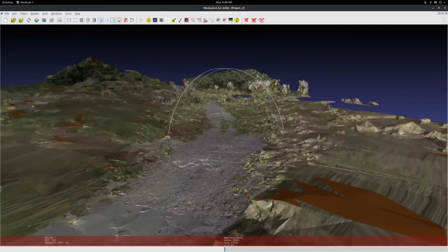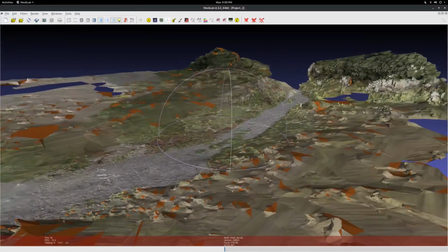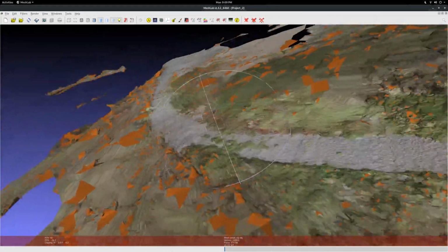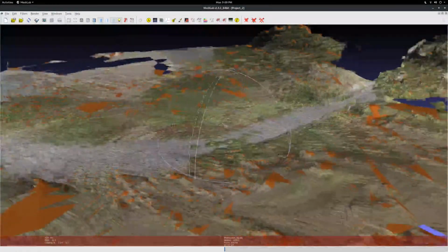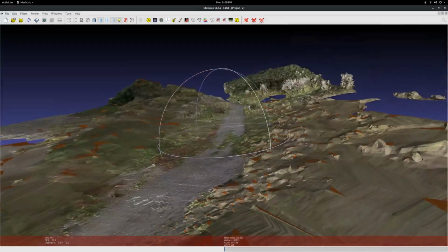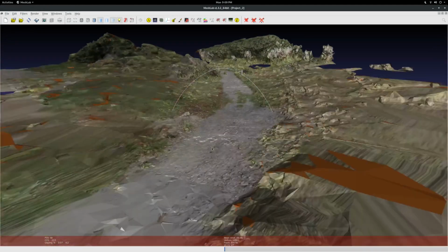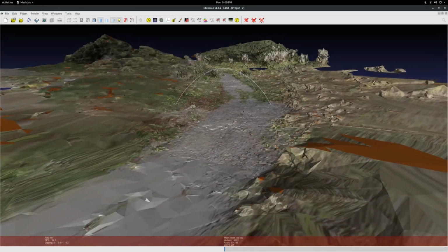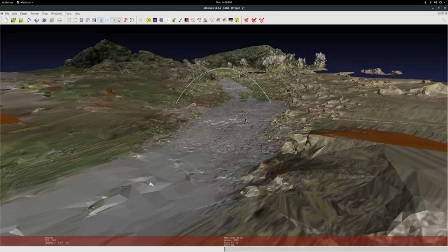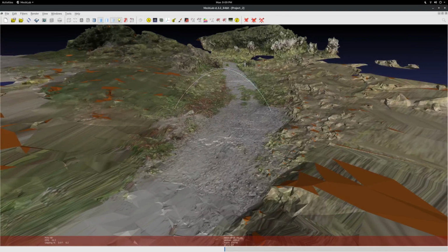If you take a look at this, this is a 3D capture of a trail. You see, unfortunately, a gap in this capture right now. But I generated this by taking video with my cell phone, and then using a process called photogrammetry, I was able to convert the video. I took 3 frames per second out of the video, took a folder of images, and set up a Google Cloud Compute instance with some software called OpenSFM, which stands for Open Structure from Motion, and then another piece of software, OpenMVS, which is Open Multi-View Stereo.